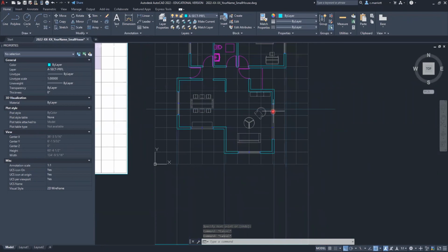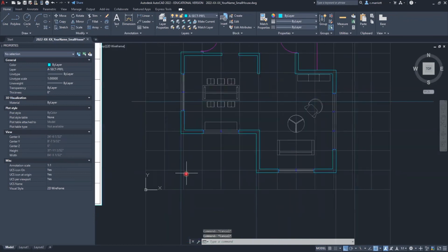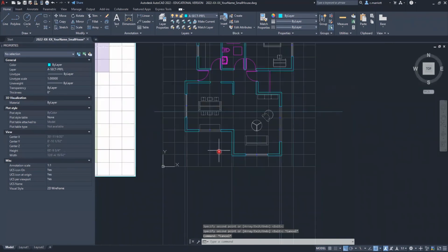Okay, now, as I mentioned, you want to draw first the stuff that we're cutting through. We're going to disregard the furniture. So what I'm going to do is make a copy of the projection line here. I know I'm going to cut through that wall, and I'm going to cut through this wall. So I'll start with projection lines in those two planes.